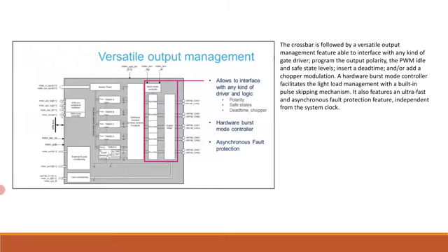This feature is able to interface with any kind of gate driver, program the output polarity, the PWM idle and safe states levels, insert a dead time and or add a chopper modulation. A hardware burst mode controller facilitates the light load management with a built-in pulse skipping mechanism. It also features an ultra-fast and asynchronous fault protection feature independent from the system clock.